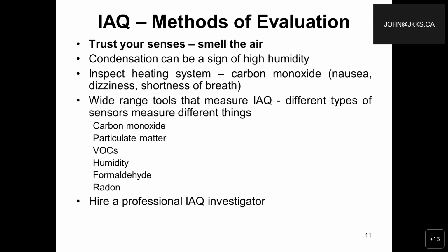Ventilation is a combination process which results in supply and removal of the air. So what we want to do is have an exchange of air, get rid of the stale, moist, moldy or mildewy smelling stuff, and introduce fresh air into the house. Condensation can be a sign of high humidity. If we look at the heating system, potentially there could be areas where we have to deal with carbon monoxide. And of course, some of those side effects could be nausea, dizziness, shortness of breath. Worst case, carbon monoxide poisoning could unfortunately equal death.